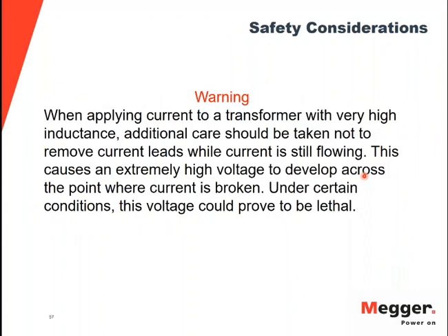So once you perform the test and have got good readings, it is very important to discharge the specimen, or discharge the winding. You know that an inductor stores energy, which means that if I don't dissipate the energy and I take the leads off, that whole amount of energy is going to dissipate where the connection gets broken, and it can develop a lethal amount of voltage which could be dangerous to the transformer or the person who is operating the leads.